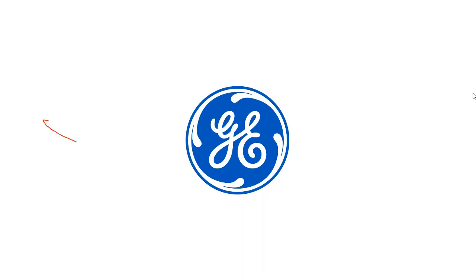So SKM, arc flash, everybody has the ability to enter a definite clearing time. You'd look in the manual and say, okay, I'm using a B90 for bus protection. That has an operate time of 1 cycle, and I have a 3-cycle breaker on the other side of that. So I put a definite clearing time of 4 cycles, and that's how I do that. But yeah, for the overcurrents, those things are in the SKM library.